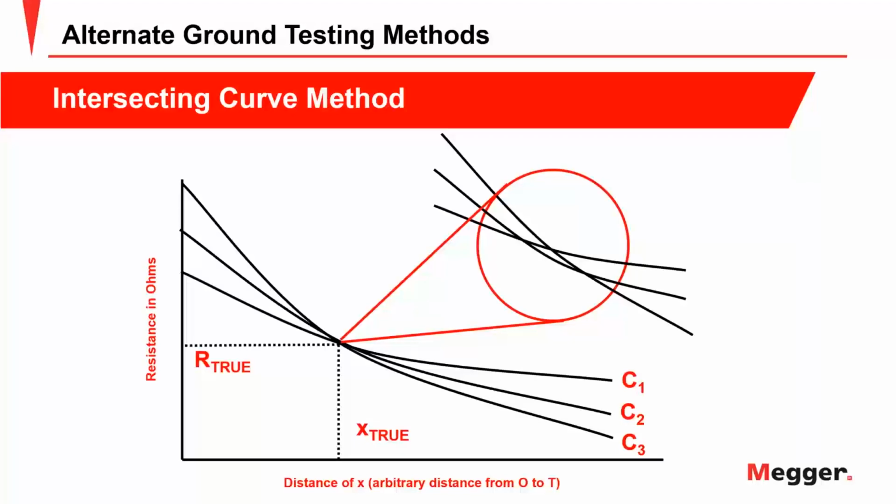And what's going to happen is the only point at which these three graphs are going to agree with each other is the correct point, the 62%, because that's the only thing they're going to have in common. That's the only correct guess. All the rest of them are wrong, but the correct point is going to fall on all three of the graphs. Or actually, like I said, if you're in a hurry, you can do two, and where the two graphs come together, you can submit that as your test result.